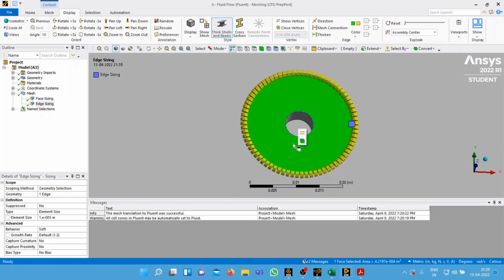So the plastic deformation is going to happen here, and it is our region of analysis. To get a good and better result, it is necessary to provide a very small element size.